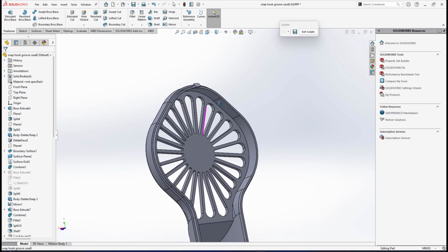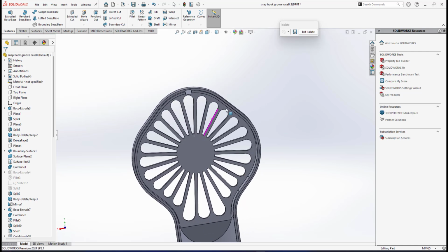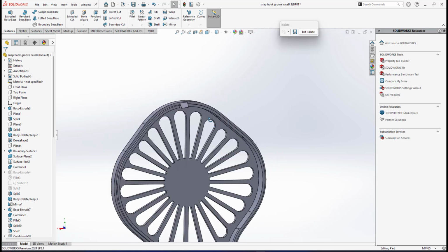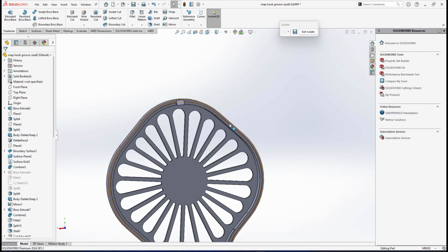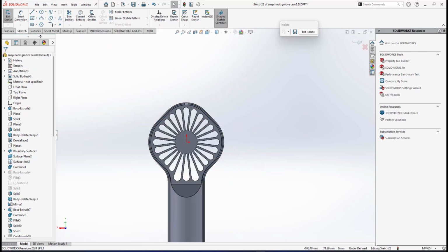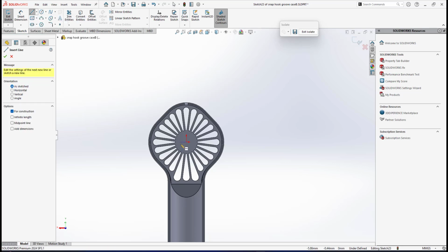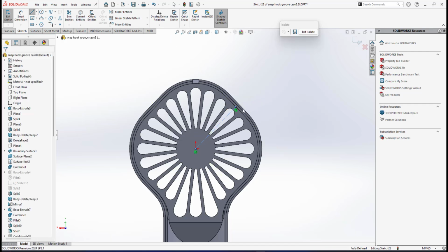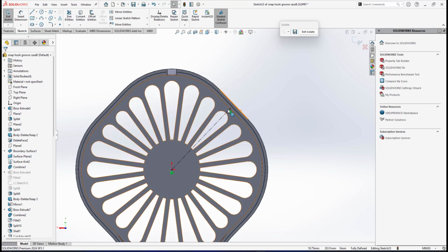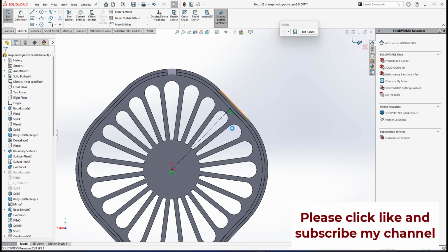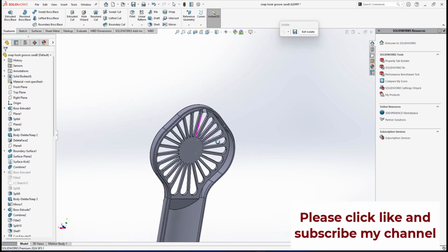Okay, here I will create a plane. I will make the second snap hook around 45 degrees from here. So at this flat plane, I create a sketch. What I will do is create a center line. This center line is for me to create a plane, and I will snap at that middle point. This is about the angle that I want, this is actually 45 degrees, snap there. So this center line will be my reference to make the plane.